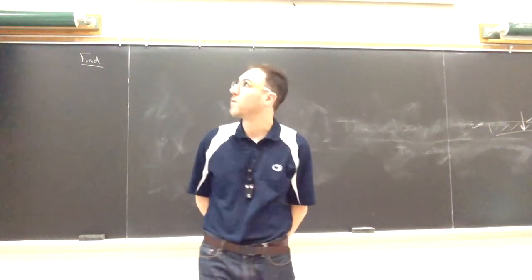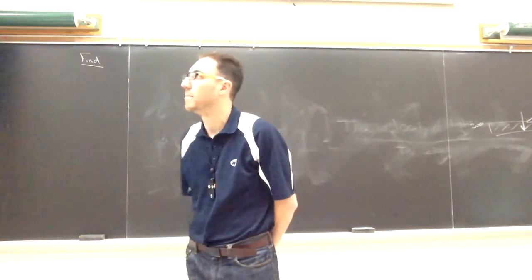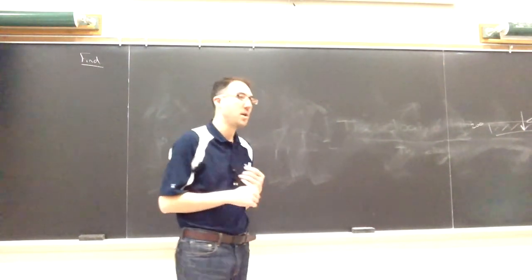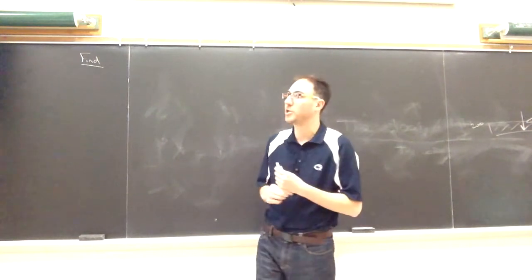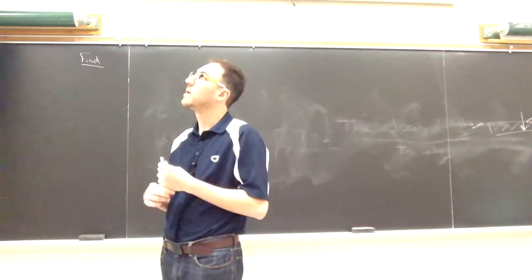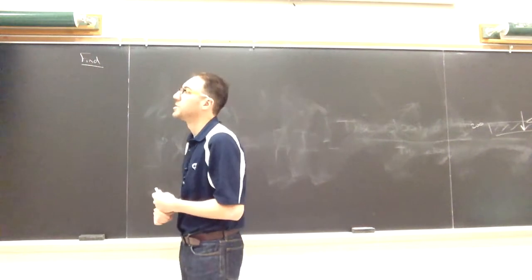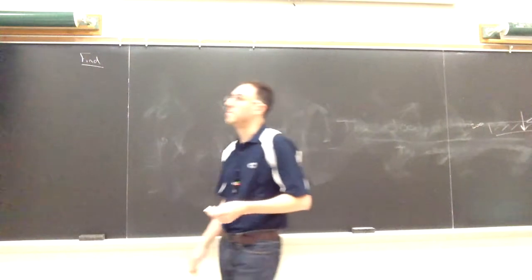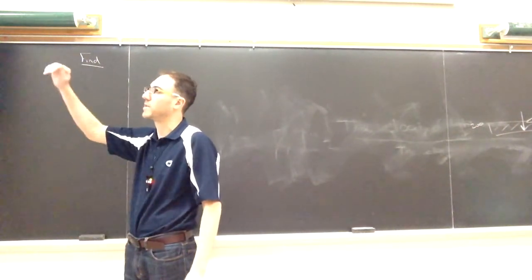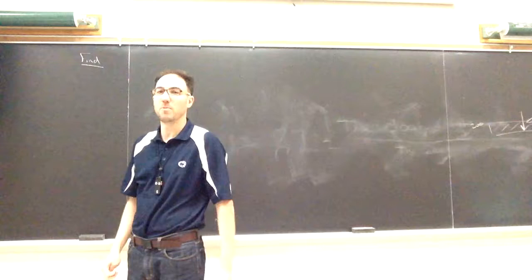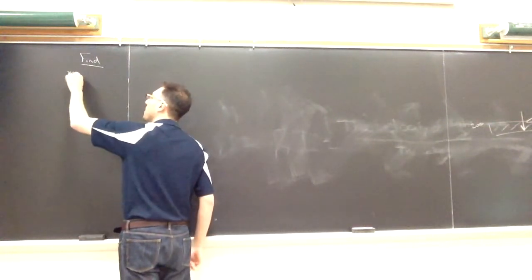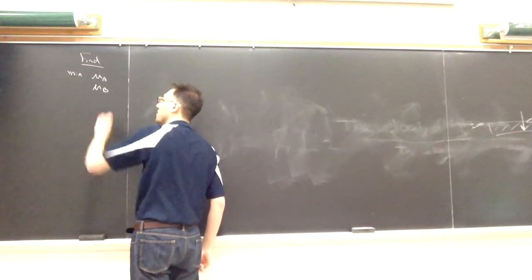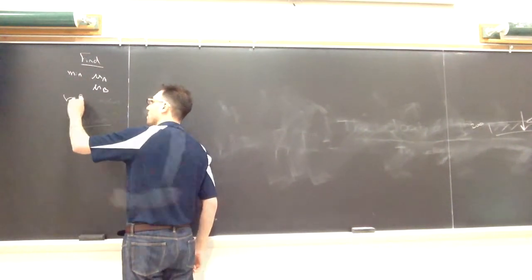If we are applying a force P of 300 newtons on this system, and we want it to not move, we're looking for the minimum coefficients of friction between the block and the spool and the ground. I called them mu A and mu B, since A is the contact point between the block and the spool, and B is between the spool and the ground. So we want the minimum values of mu A and mu B before motion would occur.